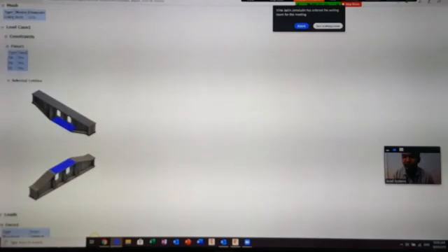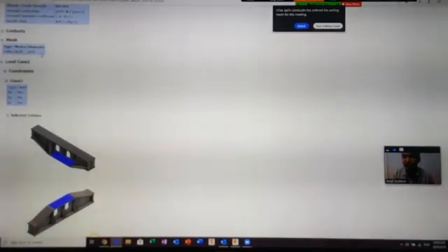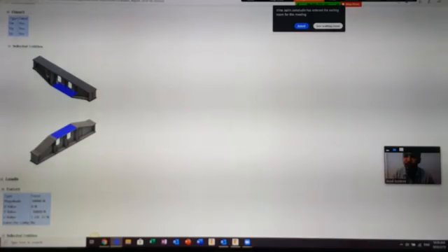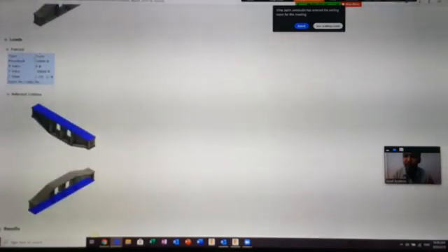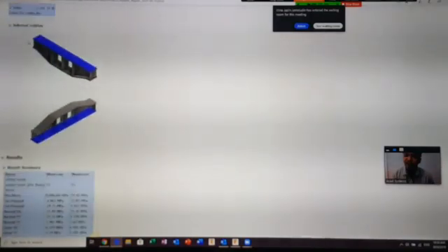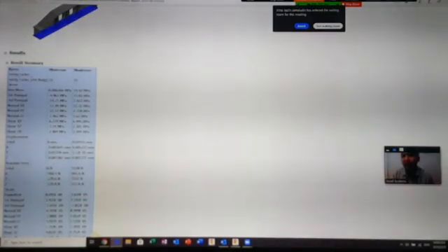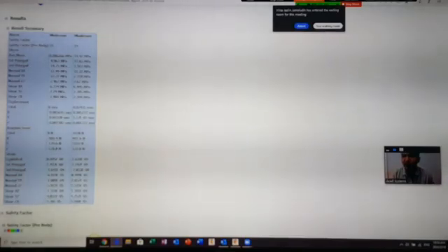So you will have the material, solid type, nodes, elements. The fixed one, the fixed location, the force. Then the entities, the selection of entities, which means the load one, and then the result summary. We have the safety factors, minimum and maximum for the stress: von Mises, first principal, third principal, normal, shear, and for displacement, everything in a table here.